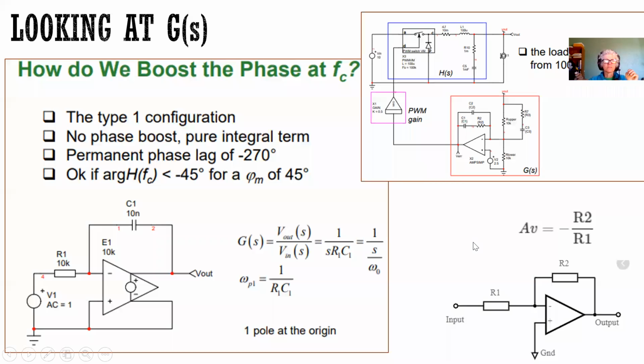So this is what that single capacitor does. This isn't exactly what I was looking for, but it moves that dominant pole over, and now your gain starts to drop earlier, and by the time it gets to the second pole and drops from there, it drops below 0 dB. Okay, that's okay, but if you move your dominant pole over, now the problem is that your bandwidth, the area that you have a constant gain, gets narrower. So there's other ways to do it.